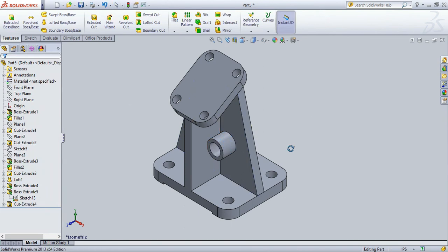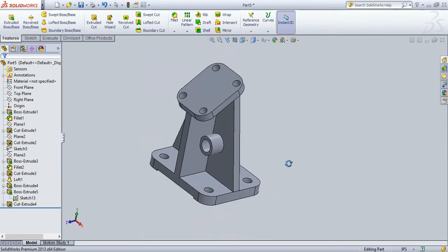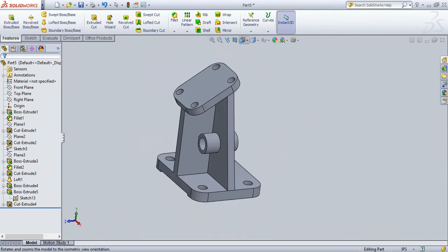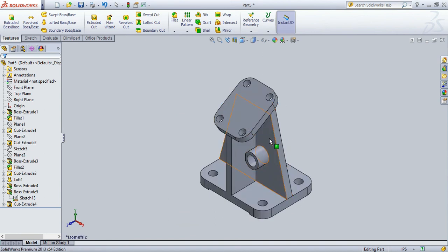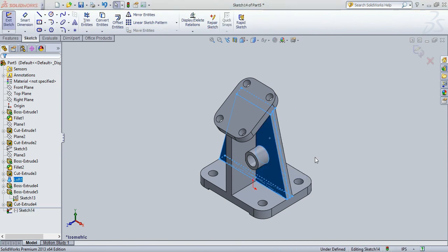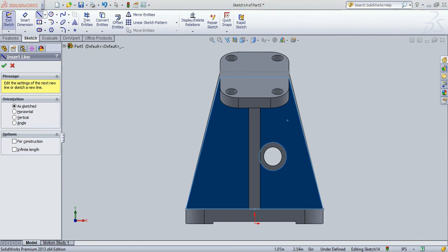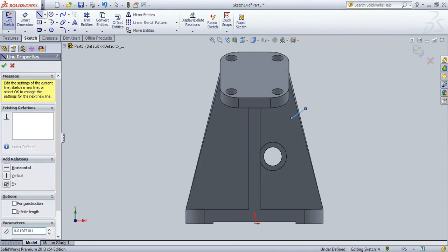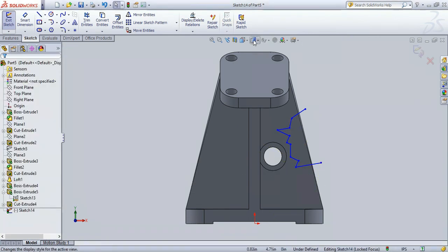So you can see it has a hole now. So basically this figure is already finished. But in order to copy the figure that was tasked to us, there should be a broken part here. So we select this as our sketching face or plane, normal to, and just simply draw a line. So line here, line there, line here, here also, there, there, there, there.